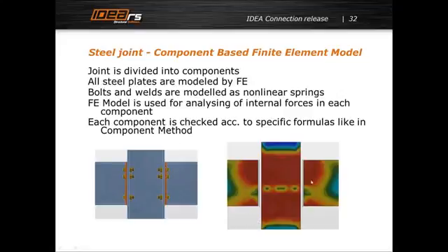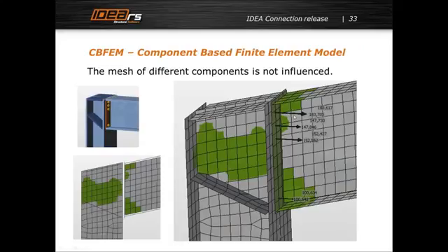We calculate stresses and internal forces in this finite element model, and then we apply the same checks as in the component method, the same checks which are in Eurocode. So it is not a replacement of the component method, but a synergy of the component method and the finite element method.